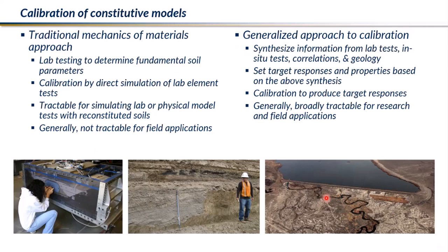When you go into the generalized approach to calibration, which is what we have been trying to promote from the use of this model, not so much in their development, you're synthesizing first all of the information you have at your site: your lab tests, the geological information, past observations, and so on and so forth. You set target responses after having reconciled any differences, and then you calibrate a model that will honor those responses. The constitutive models, it doesn't have to be PM4, it could be any model, will not reconcile issues that you have from the field characterization, and it's important to separate that.